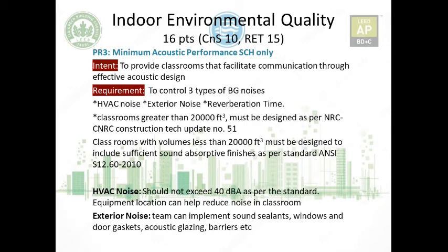If you can place the equipment, which is the usual practice, even in the houses, the people who are familiar with design usually put their equipment either in the corridor, or somewhere in the kitchen, or in the bathrooms. You do not put it in the bedrooms if they are centralized equipment. So this is one strategy to avoid the background noise of HVAC by placing it in areas away from where communication happens, or out of the classroom.